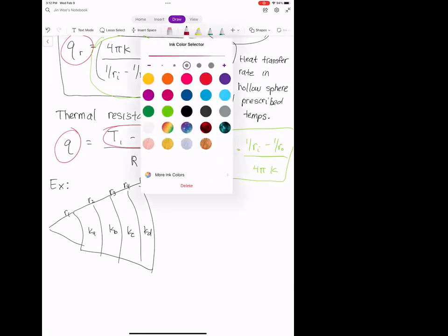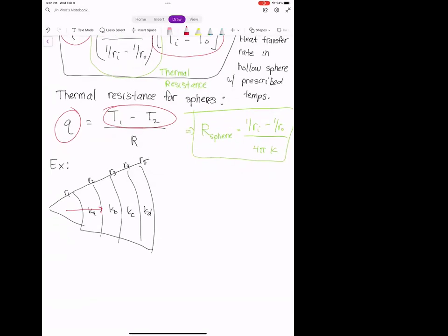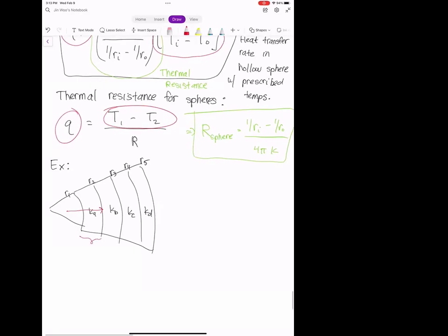Right, and let's say that we're interested in computing the amount of heat that passes through the sphere, right? But if we have 4 different layers, it makes it kind of a pain to use with the heat equation. Okay. But in multi-layered systems like this, a thermal circuit does a really nice job of making it simple for us, right? Because what we can do is take each layer here and represent it as a thermal resistance.